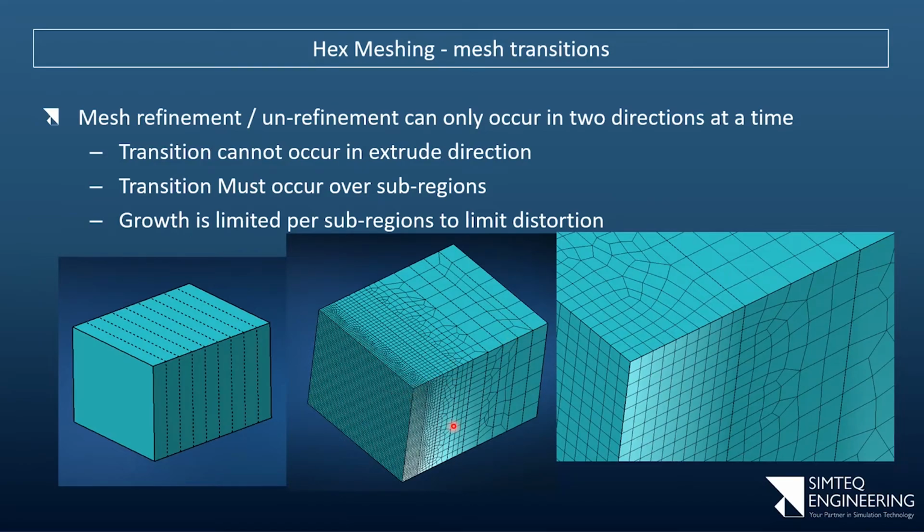And another issue that is also visible here is, yes, I know there are horrible elements, but I've kept it like that so it's easier to visualize what's happening, where it's fine and coarser. But one of the things you may have to do is use thinner slices for the fine mesh, and as you go coarser and coarser, you may need more and more elements in that direction to be able to transition decently from a coarse mesh to a finer one, or sorry, fine to coarser.